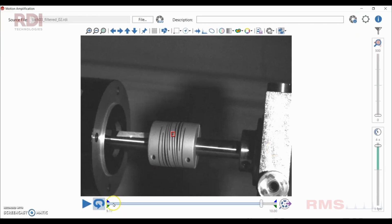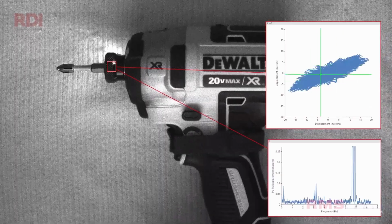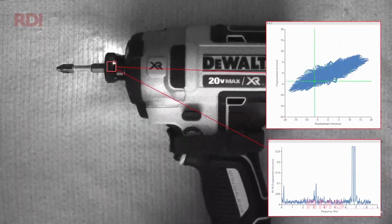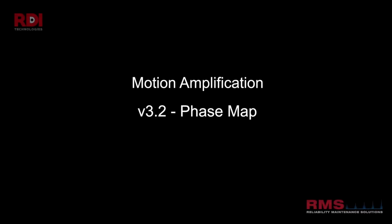Now here's a coupling, this is rotating, and that's the standard video. We're going to amplify it now, and we can actually see the coupling flexing. So this is the non-synchronous frequencies we're looking at. It removes the one times, okay? This is a fan impeller. We can see there's a little drill there. Absolutely amazing. I'm looking forward to getting some industrial shots for this, but truly amazing.